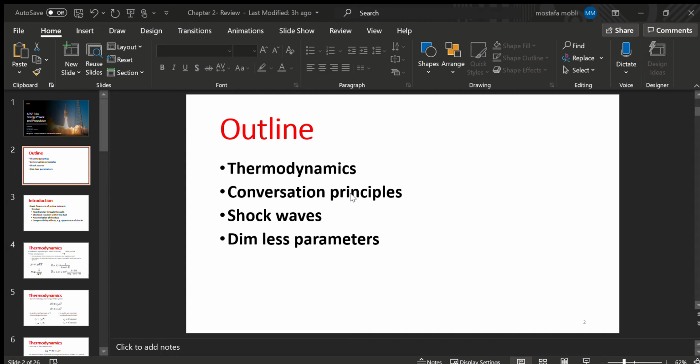So essentially, you can take the integral: the entropy of the second state of the system minus the entropy of the first state of the same system, delta S, the change in entropy, is the integral of CpdT over T minus R natural log of P2 over P1.